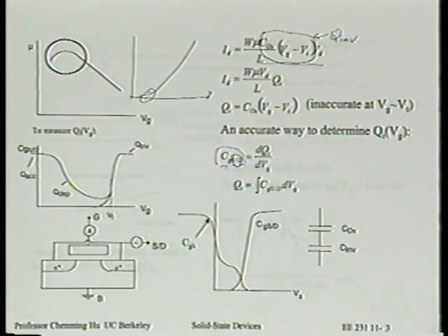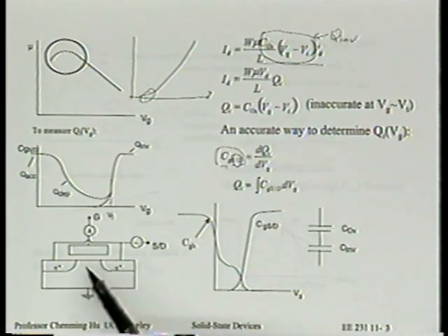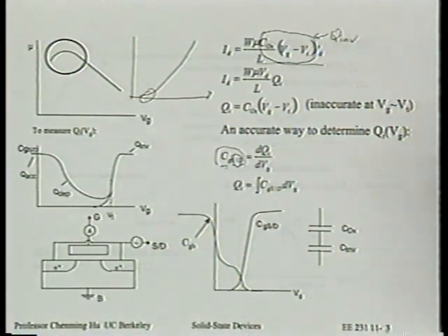So together is one terminal, one node. Source drain is only one node. We measure the capacitance between that node and the gate. What are we getting? The simple way to think about it is to start with the strong inversion case.